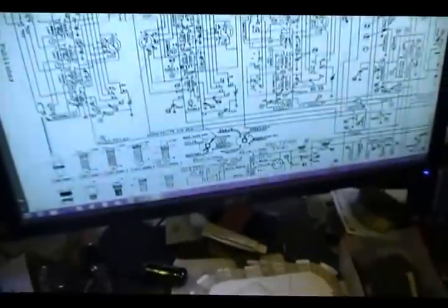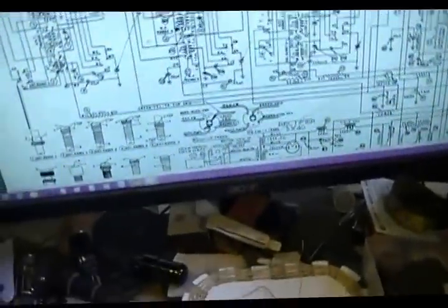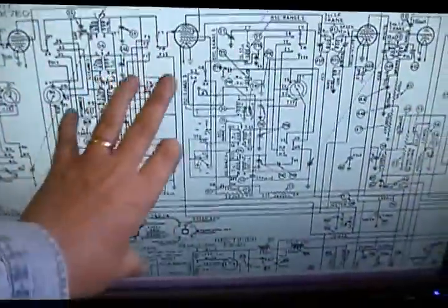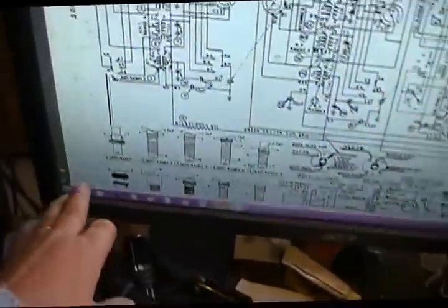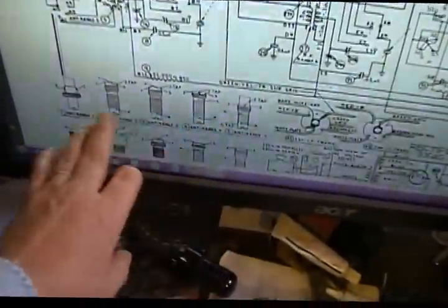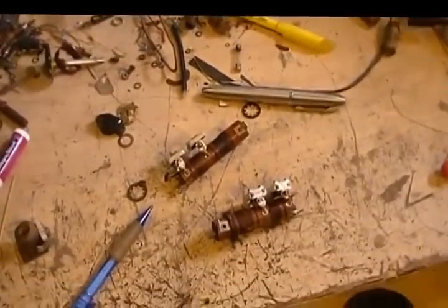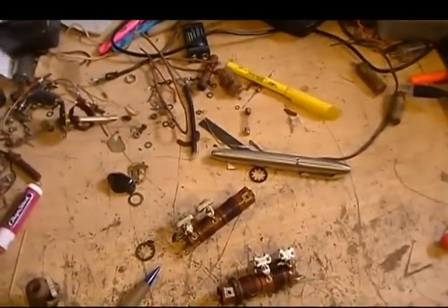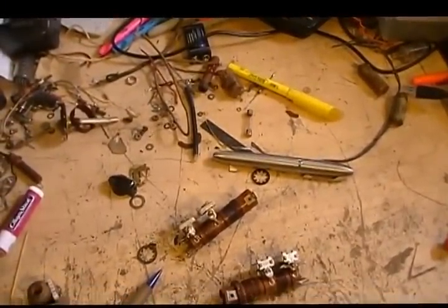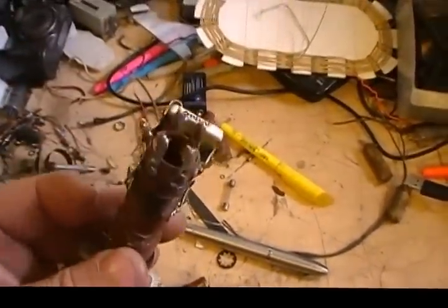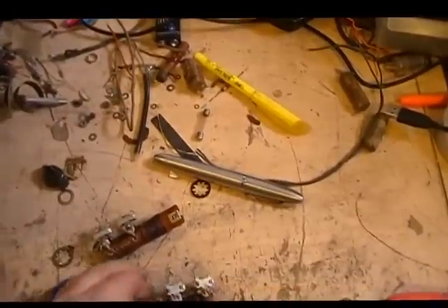So you should study it long before you ever pick up these guys, before you ever take anything out. Study the schematic, know where everything's at, and understand what they've documented in the coils. Make your own documentation, take your own pictures, do all this, and you will be less likely to ever get in any trouble of not knowing where to hook things up.